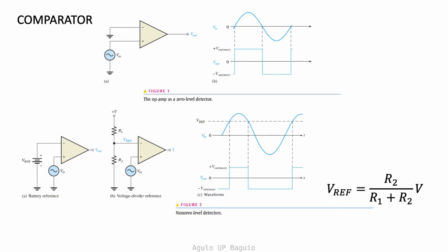In Figure 1, the reference signal is ground or 0 volts. Every time the input signal crosses the 0 volt reference point, the output switches from one saturation state to another. For example, in the figure, the signal begins just below the 0 volt reference. As soon as it crosses 0 volts, the output signal is positively saturated. As long as the signal is positive, the output will remain saturated and at maximum. As soon as the signal crosses the 0 volt level again, the output signal then becomes negatively saturated, or at the